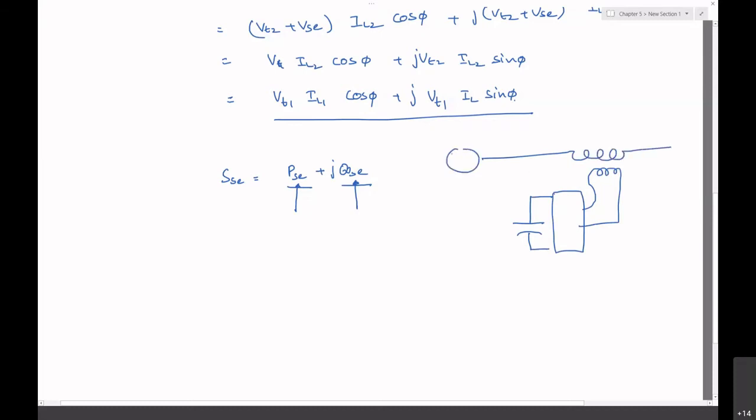This is the source over here. When you try to make the correction with a VSC and a capacitor, it tries to inject only reactive power. But as we see in the phasor diagram, voltage correction is possible only with the injection of both real power as well as reactive power.